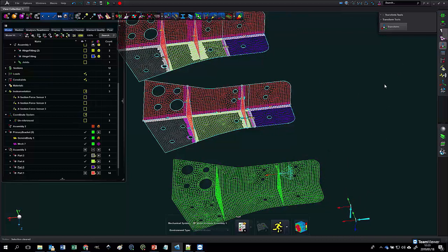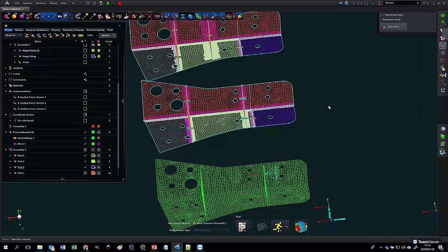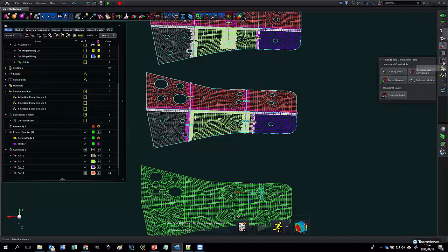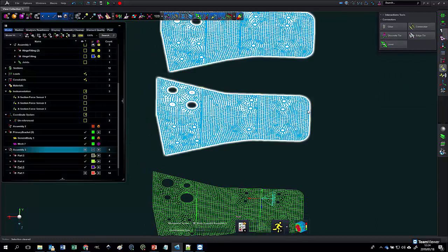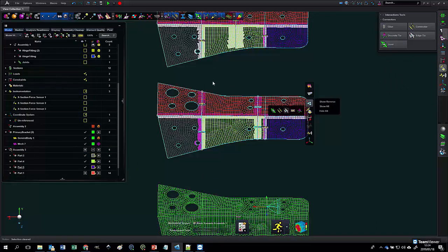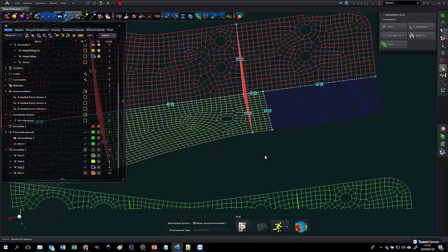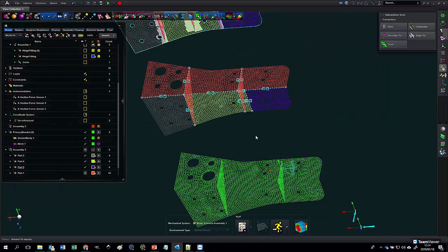RBE connector. I just see that I have some glue created here that I've accidentally overlaid on top of the tied entities, so that can be deleted. To do that properly, I need to just switch to glue, and I can see the rendering of the glue and just delete them. Okay, so we get a clearer image of the ties alone.